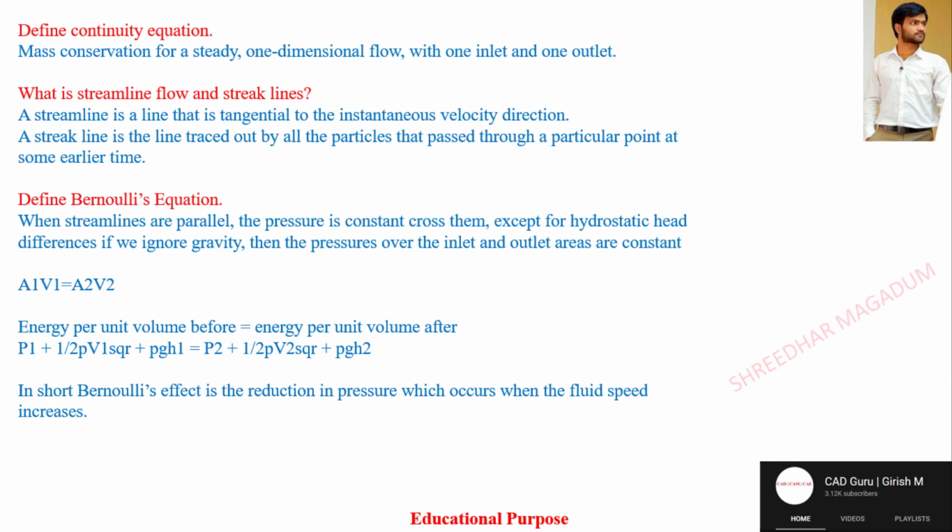Bernoulli's equation. When streamlines are parallel, the pressure is constant across them. Except for the hydrostatic head difference, if we ignore gravity, then the pressure over the inlet and outlet areas is constant. Okay, and then A1 V1 is equal to A2 V2, you can consider this equation.